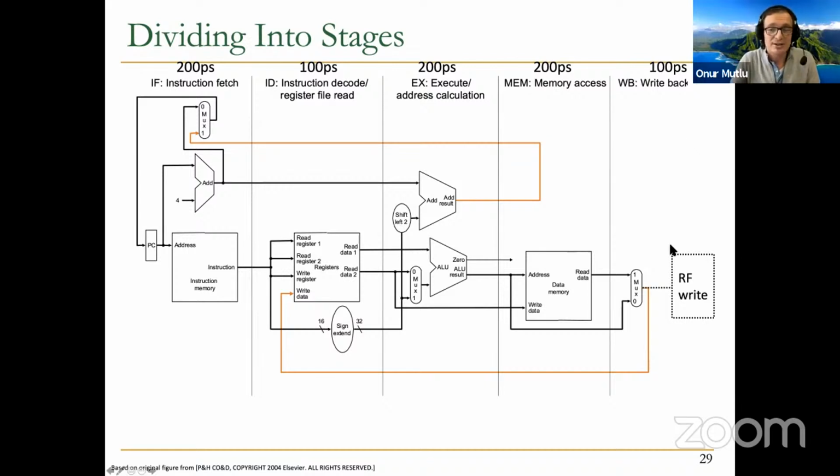So basically, we write to the register file at the end of the pipeline. This ensures that we obey the von Neumann requirement. The von Neumann model dictates that instructions write to registers and memory at the end, basically. And that's going to happen. Architectural state updates are going to happen at the end of the pipeline. We're going to get back to this, but we're going to preserve the semantics of the von Neumann model by doing the architectural register file and memory updates at the end. So ignore for now some of the things that need to go back.